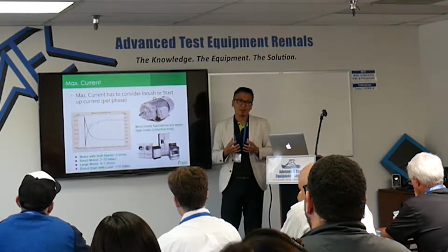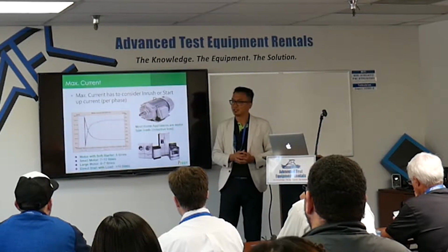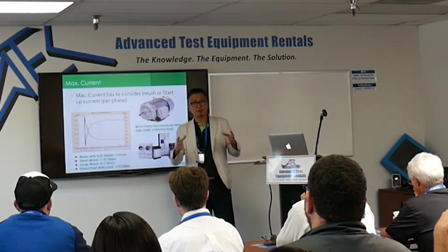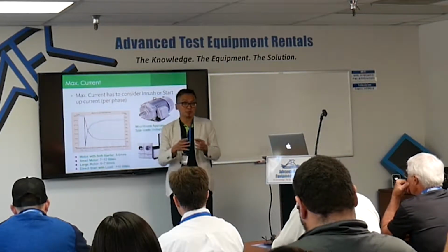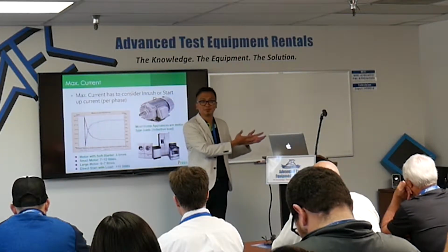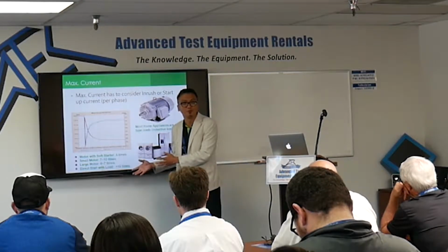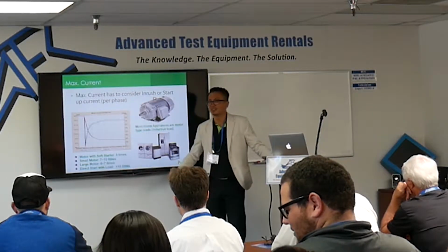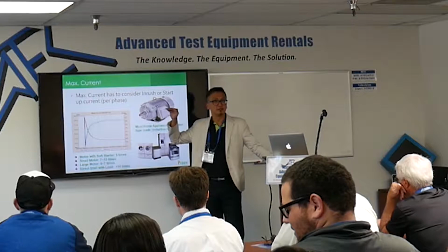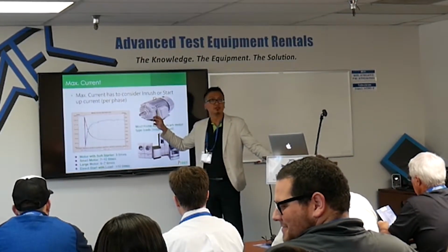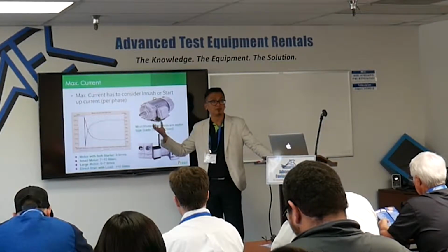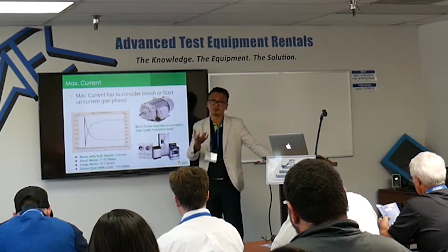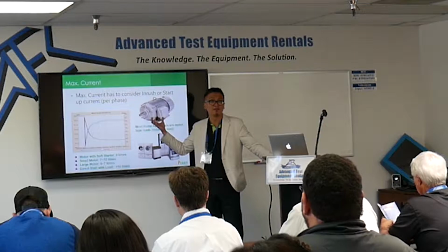The best way I would tell the customer is, can you measure it with your scope and check the current. You can power it just from your wall outlet or something like that, and check the maximum inrush, or go back to the original manufacturer. Usually they have the spec for that, and they will test it for you and give you the spec of how much inrush they have.